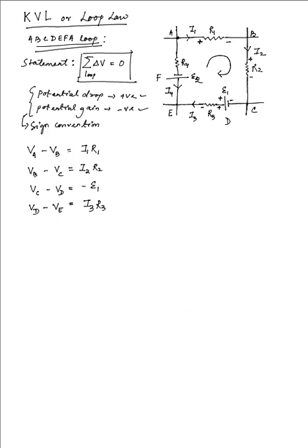Now with that available, we move from E to F, VE minus VF, and that has to be equal to plus E2. Why plus E2? Because as we are moving from E towards F, forget about the current over there, because the current, although maybe in the downward direction, we do not have any resistance present over there, so the resistance is above that, so we are just having the potential difference in case of the cell that is available.